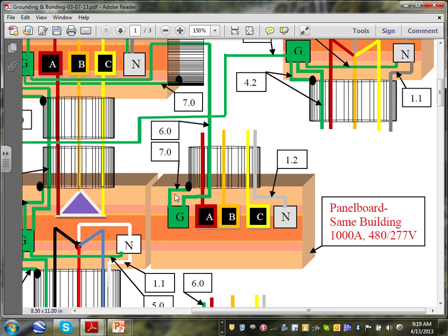If my overcurrent protection device is right here, anything on the line side has minimal short circuit and overcurrent protection. On the load side, if you design it well, you should have a proper overcurrent protection device, because you have the main circuit breaker to protect you from arc flash and short circuit and everything else. And if you're downstream, you also have the feeder overcurrent protection device to protect you. That's why the code treats them slightly different.